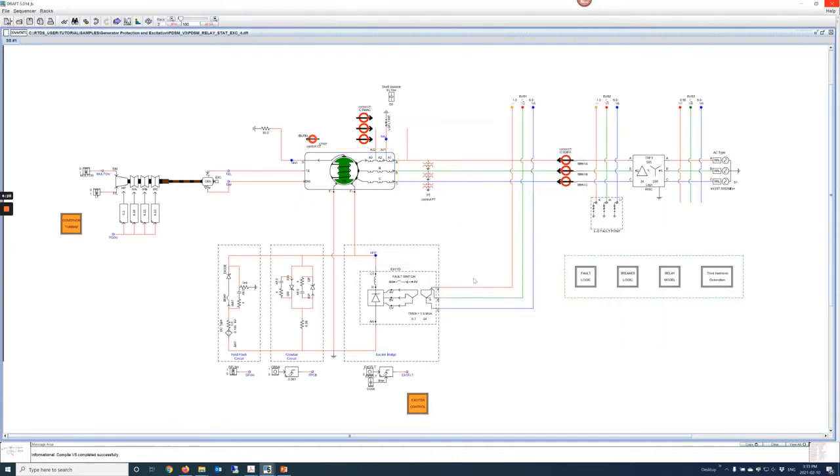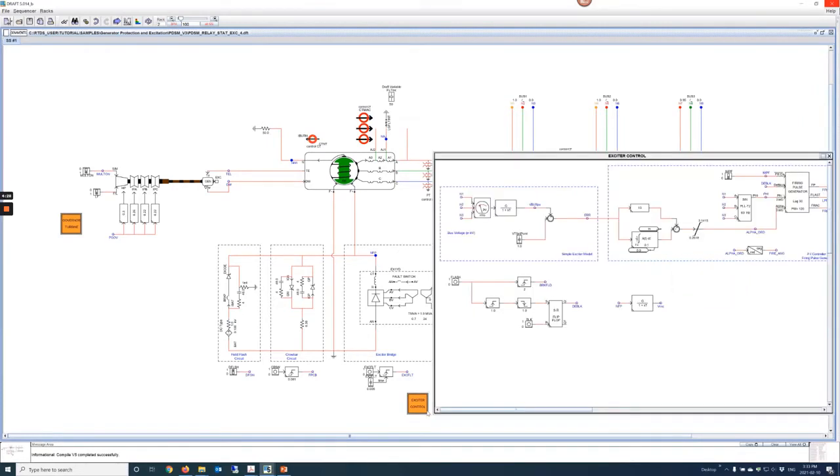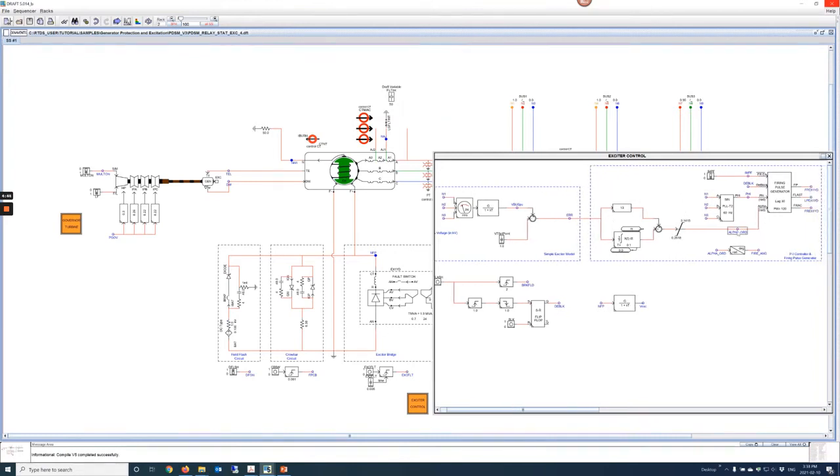Now let's look at this excitation system. AVR, or the control part of excitation system, is modeled here in this box. We're receiving terminal voltages, filter them, compare them against a set point, putting in a simple PI controller, and find out alpha order for 6-pulse valve group and prepare fire impulses for that valve group.